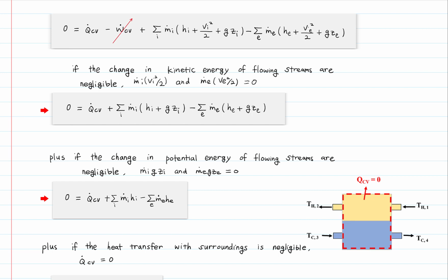If we take the entire heat exchanger as the control volume, Q dot is 0, as long as there is no heat transfer between the heat exchanger and the surroundings. If one of the fluids is selected as the control volume, heat is transferred across the system boundary, so in this case Q dot is not 0. Note that the basic energy conservation principle is valid no matter how we select the system boundaries. We need to determine the system boundary based on the information we want to determine.